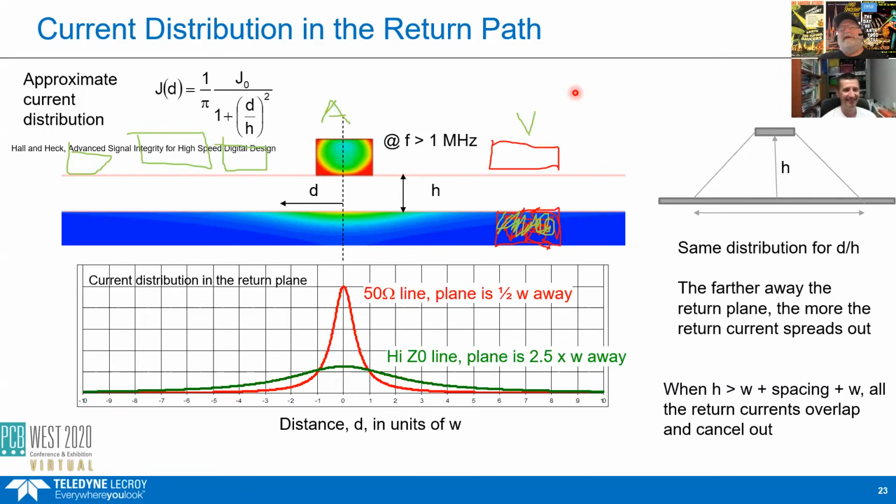The only way we can answer that question about crosstalk between two adjacent lines is that it's all about the fringe electric and magnetic fields. The only way we can answer how much crosstalk there is, is using a 2D field solver, because it's the only way to calculate those fringe field lines. And that's a very simple, straightforward calculation.